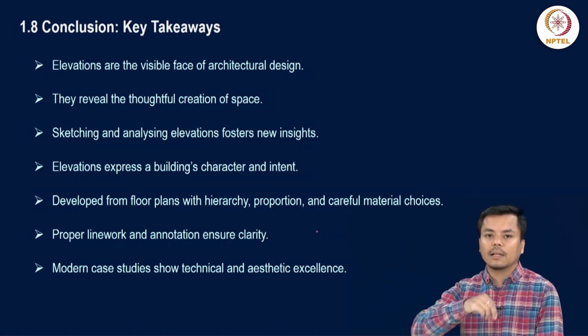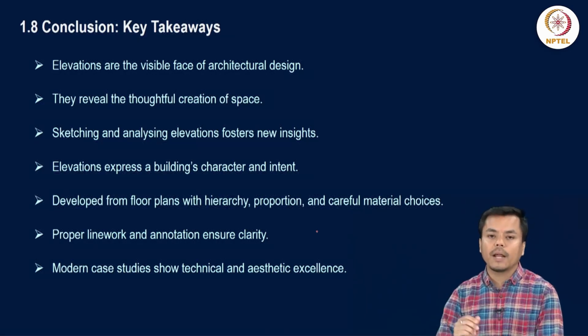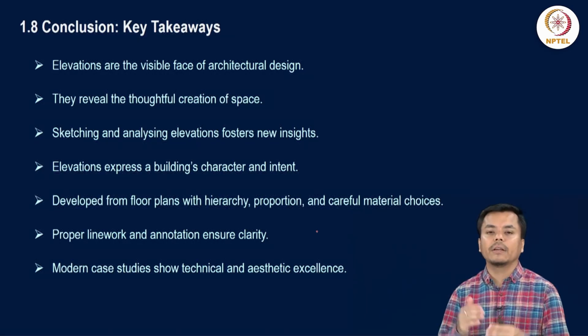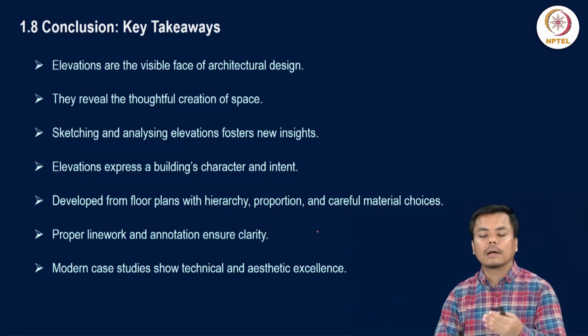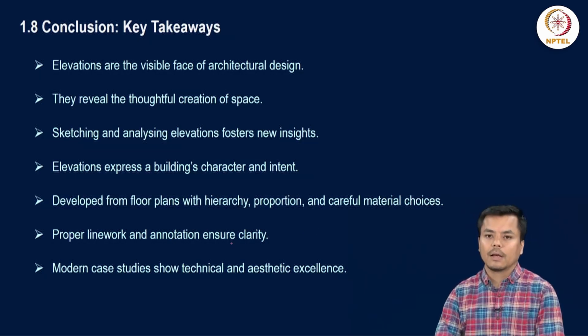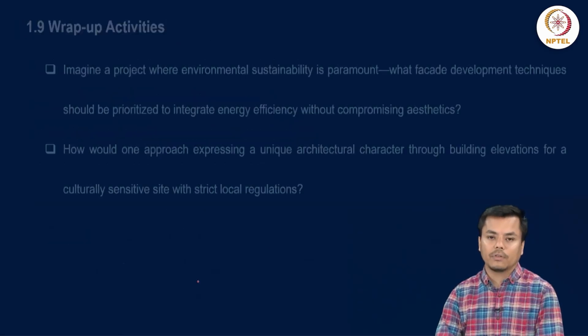Always project the lines from your floor plan so that the dimensions are accurate and you are able to draw the section of the structure more clearly with fewer errors. Proper line work and annotation ensure clarity in your drawing. Modern case studies showcase how technical and aesthetic excellence can be achieved through the elevation of the structure.